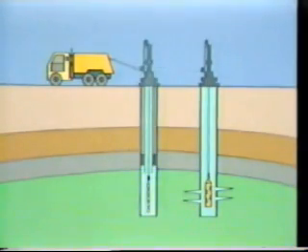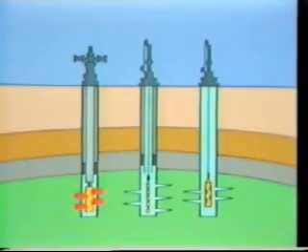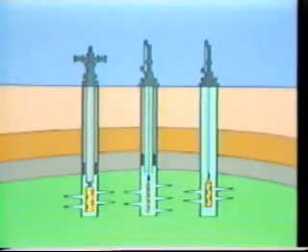Conventional underbalanced perforating is usually done through tubing with an underbalanced well bore, that is, a small head of fluid in the tubing to allow immediate flow when the perforations are created. And tubing conveyed perforating is where the gun is run on the bottom of an empty tubing string, allowing the maximum amount of underbalance during perforating.